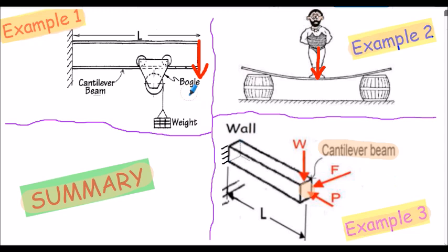Hopefully you've attempted the exercises associated with the 3 examples. For reference, exercise 2, which was based on example 2, comment on what was noted about the results of exercise 2 compared to example 2. The only difference between example 2 and exercise 2 was the applied load, and as we are considering a linear static analysis here, you should have found that the stress, the factor of safety and the deflection are proportional to the applied load.